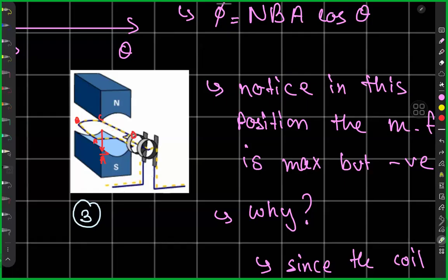And over here, if that is B and this is A, your right hand grip rule will indicate your thumb in this direction because it is creating an out of the plane magnetic field. The flux change is inducing a current in the coil such that the induced current creates its own magnetic field out of the plane to compensate for the increase in magnetic field lines into the plane, that is of north and south.